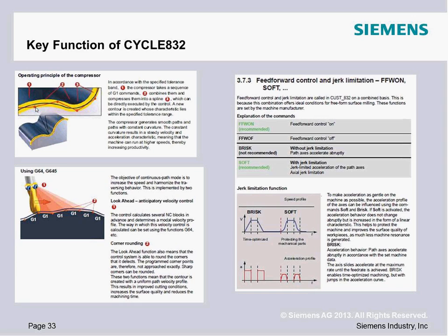If I'm roughing, I usually put about a 5 thou chordal tolerance. If I'm semi-finishing, I typically drop that to a thou. And then finishing, I usually set that to half a thou, 0.0005. At least a starting point, and you can work with it from there. Move it up, move it down. But if you know what that value is, a discrete value, you will use that value.